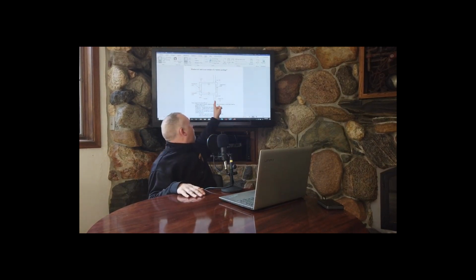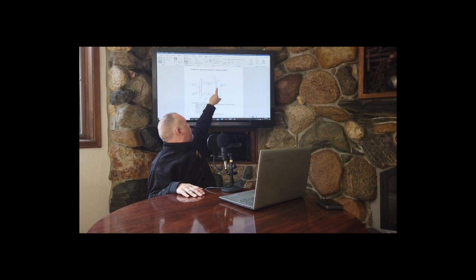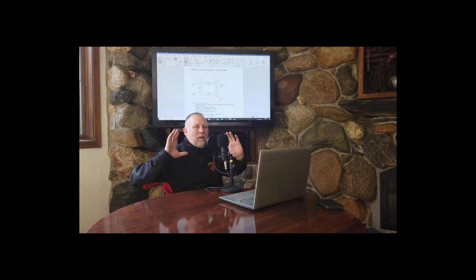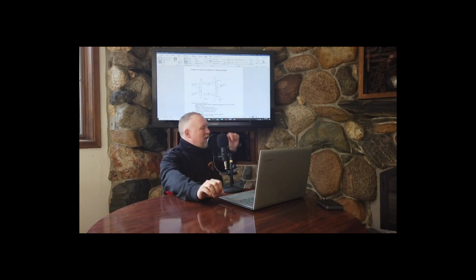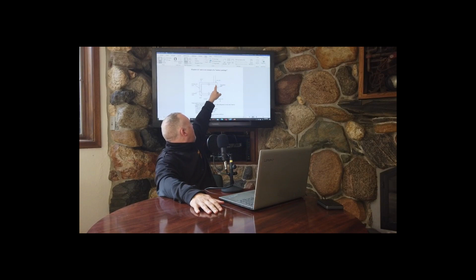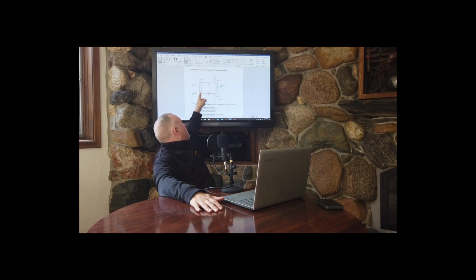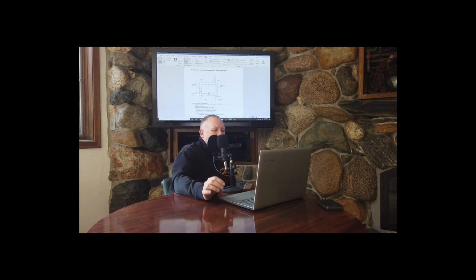I have to go to a window. Notice, this is inside the building, outside the building. The evaporator faces inside. If you put the window air conditioner into the wall, the part that's facing you is the evaporator. It's what makes things cold. Room air comes in, passes through the evaporator, and then blows out. You stand in front of it, you get that cold air. On the outside is the condenser. That's outside air, blows across it. And then the compressor and thermal expansion valve and all the piping is all inside this box. This is a window air conditioner, unitary packaged.